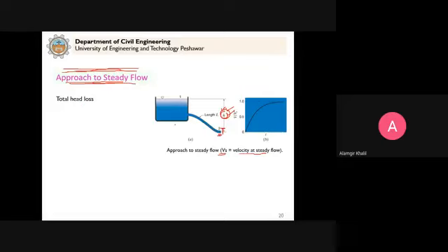So now, because the frictional effects and the minor losses have an effect on that, the total head loss is given by this equation here. Now remember, this is all the losses. This doesn't mean that this is only the minor losses. No. Whenever the term HL is written in your textbook, it is all the losses, major plus minor. We studied that HL is equal to HF, the head loss due to friction, plus H dash. So that's why it is all.